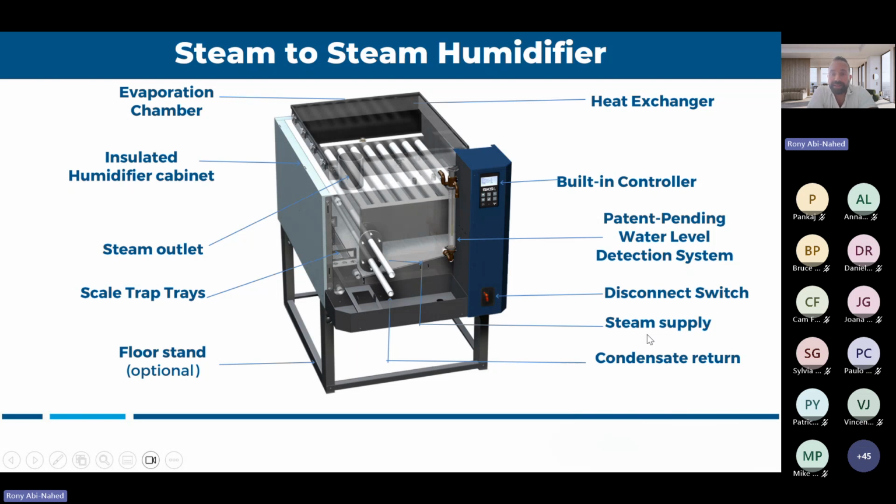So what they do is take the steam from the boiler, pass it through the steam heat exchanger, fill this tank with fresh water, get it heated by the steam in the heat exchanger, and you get clean steam out of it. Some people will call it a clean steam humidifier. Some people will call it a steam to steam humidifier. It's the same.